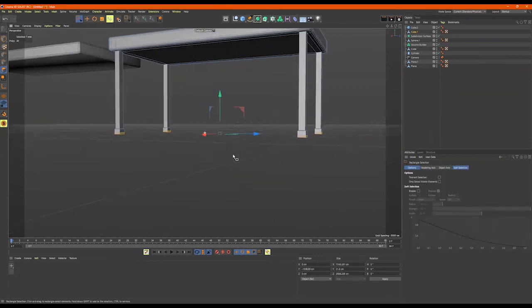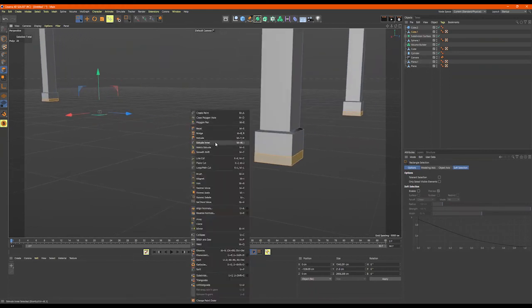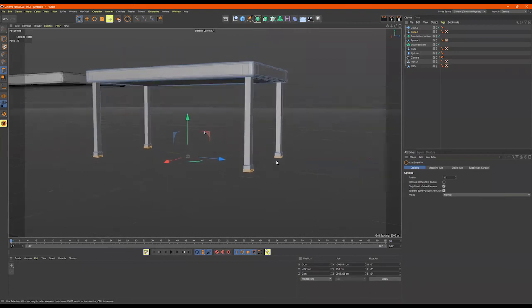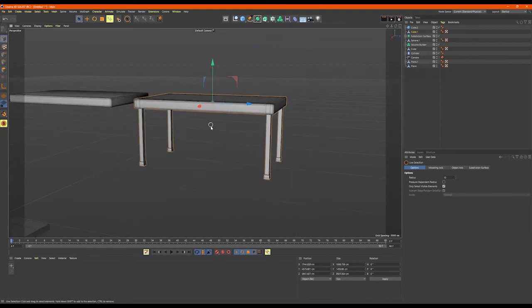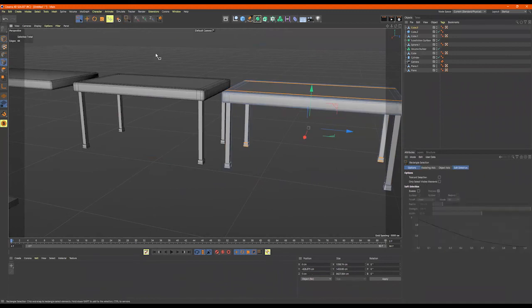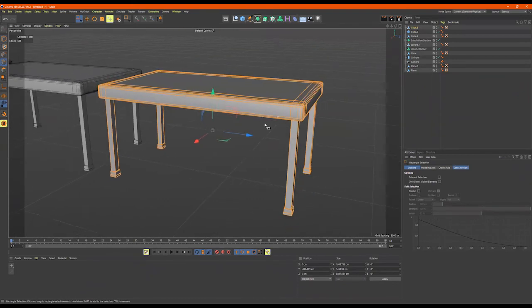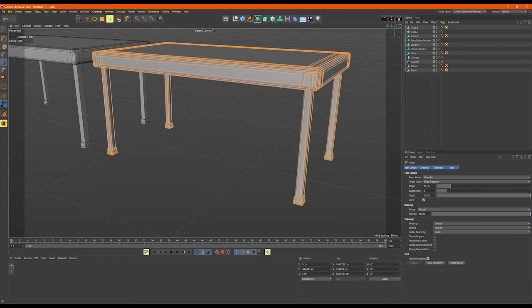So I can just grab these extra faces on the bottom and do that same thing again. Extrude. All right. Just for a little experiment, I want to see something. If I get these edges right here on everything, and sometimes I'll do this, I'll make another object just to experiment on. I just want to see what a bevel would do.